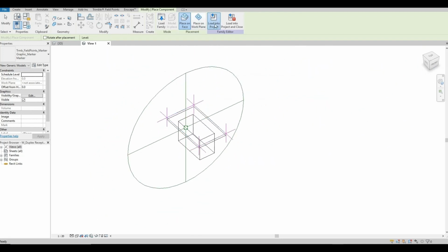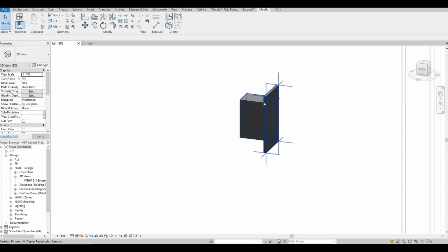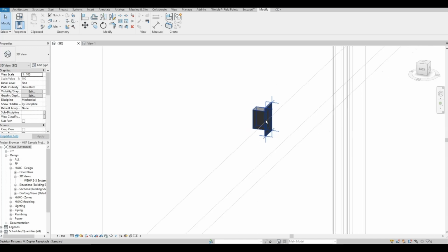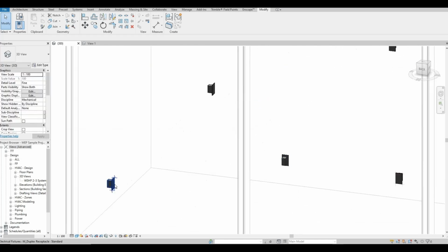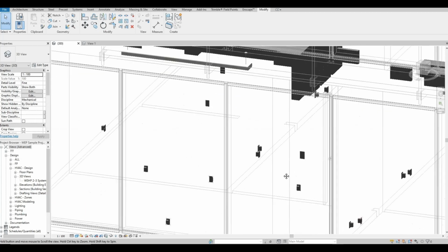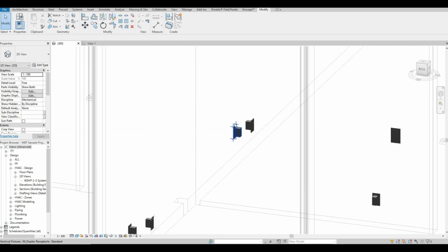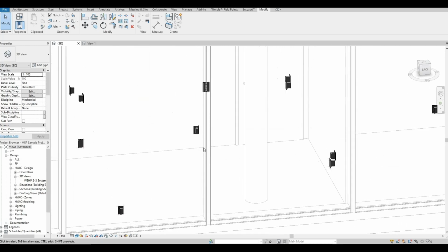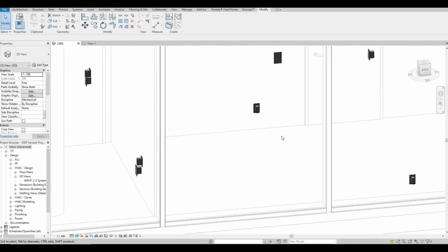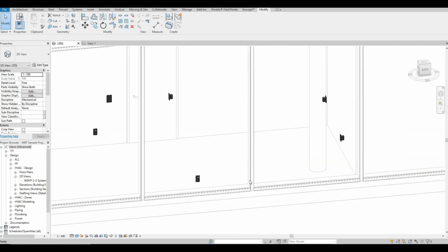This I can now load into the project, overwrite my existing version, and what we'll see on each of these receptacles now is those 4 points appear. Those 4 points will stay within the family. We can see them just popping up there. Any one of those receptacles, we can just about see them poking through some of the walls. So I now have the ability to generate the setting out points automatically. You'll notice as it's in the Revit family, the rotation and the position do not affect the position of the set out points that we generate.